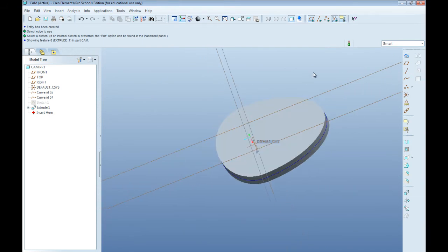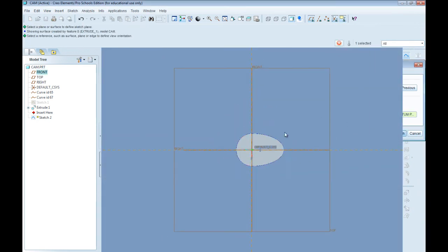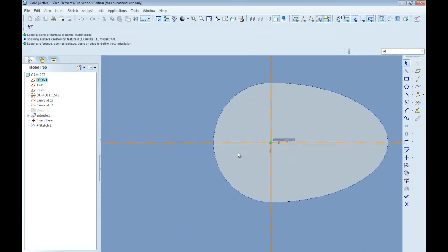What we're going to do next is create the holes that are used for the beams or the axles to insert. Let's click Sketch here. If we're familiar with Lego axles, we know that they're not circular, but cross-shaped. That's used to mesh with the parts to allow them to rotate. Wheels rotate the same way. They mesh with the axles, and they're driven by gears and motors.